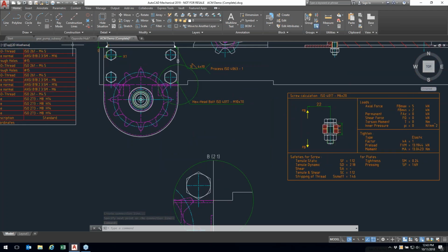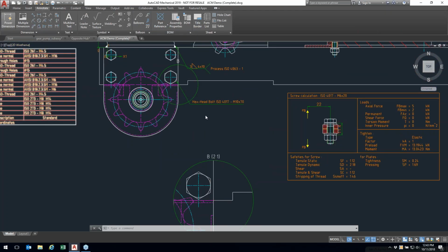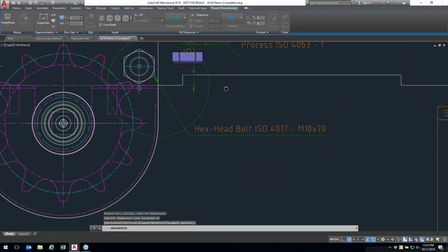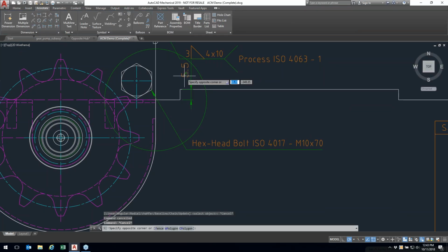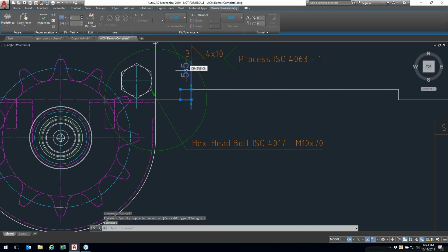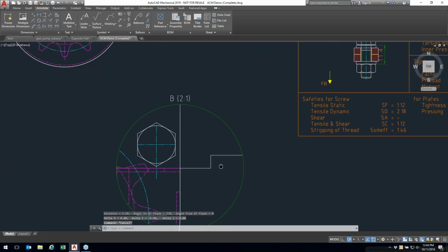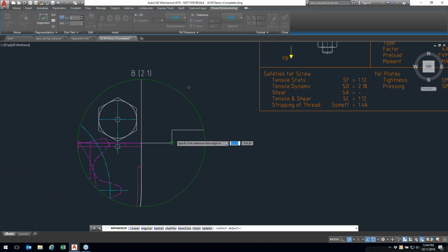Now, the real power of this is if I go to my power dimensioning command, for example, and I dimension things like maybe this thickness. When I dimension it inside of this view, it gives me the correct value, the 5.5 millimeter gap. And obviously I have the full controls there. Just to show here, I'm going to run a quick distance measurement from point to point, and it is 5.5, right? But if I go to that other area and I run the same power dimension command and select that same object, the dimension still comes out as the right value.